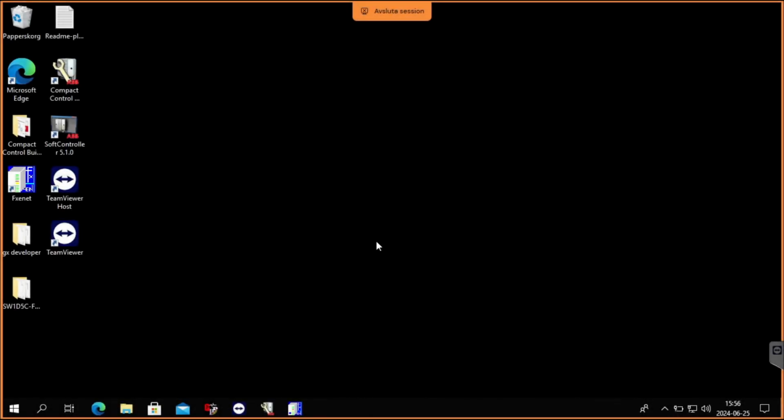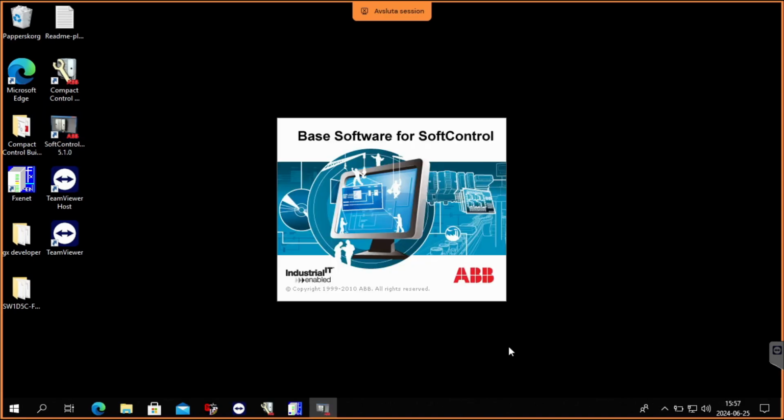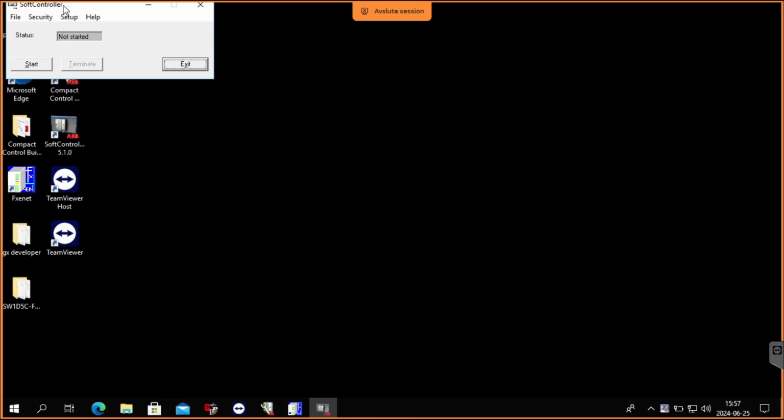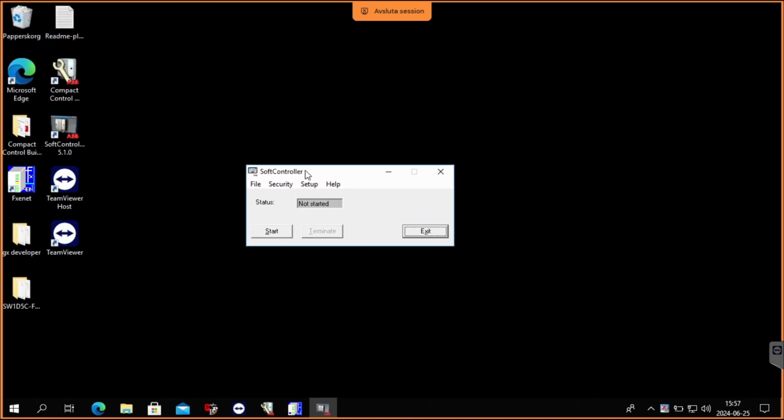In today's video we will go through how to set up a simulation in Compact Control Builder. To start a simulation we need this software called Soft Controller. It is included with Compact Control Builder. All we need to do is to click on the Start button to start a simulated PLC.